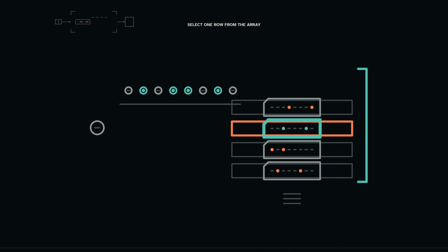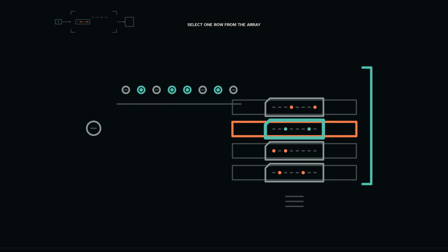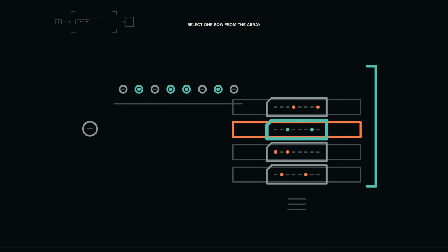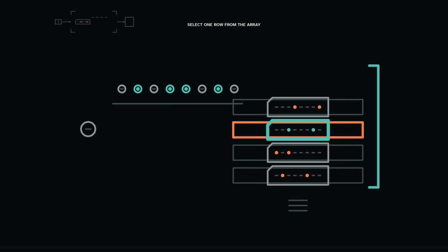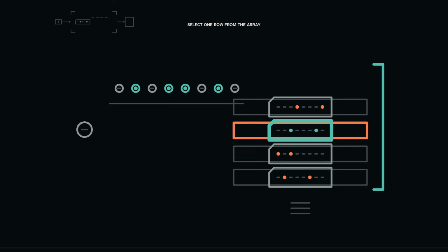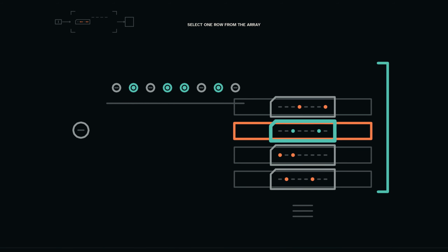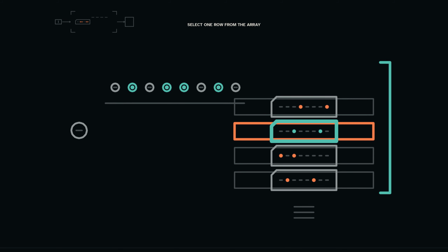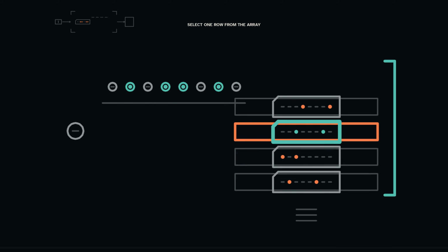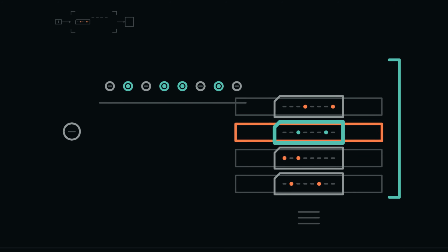SE8 has 256 address selections, but only hexadecimal 00 through EF connect to its 240 ordinary RAM rows. The upper 16 selections are reserved for devices. Nor is this a transistor for transistor portrait of modern dynamic RAM. Real memory technologies differ in cell design, refresh, timing, buffering, and hierarchy. The truthful promise here is narrower. An addressed RAM byte can be read, and an authorized write replaces exactly that addressed byte.